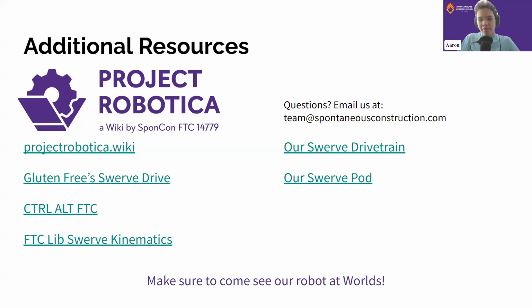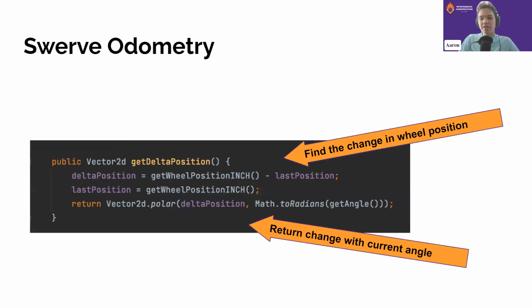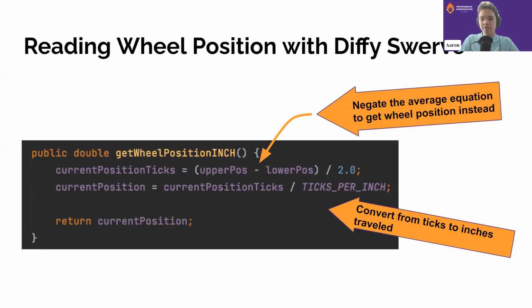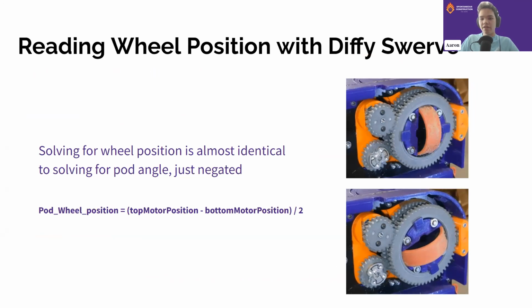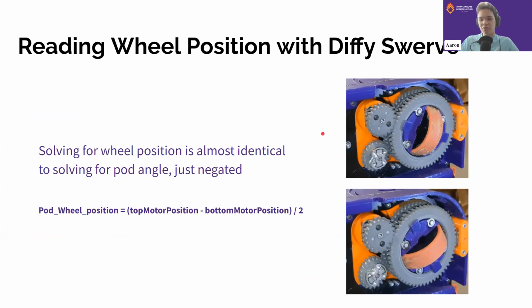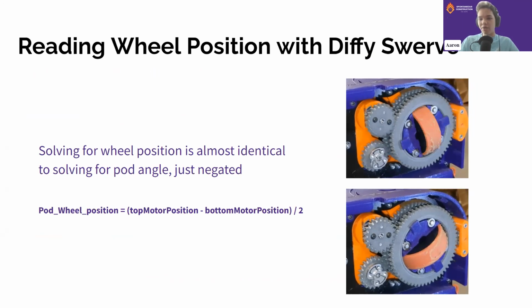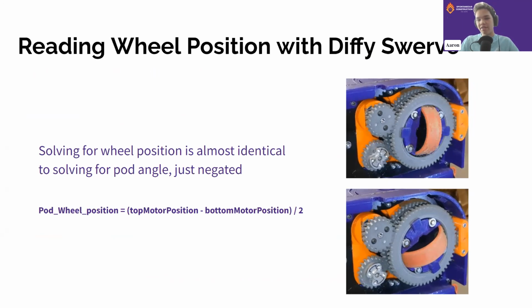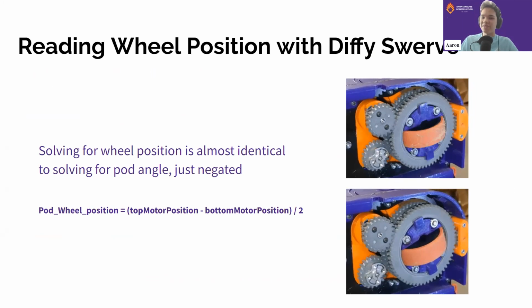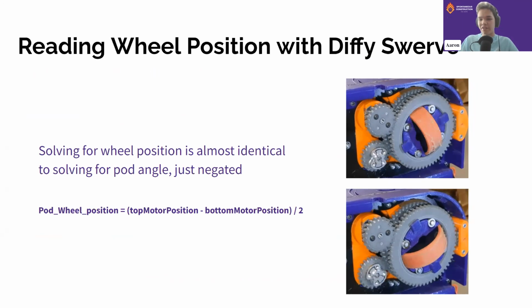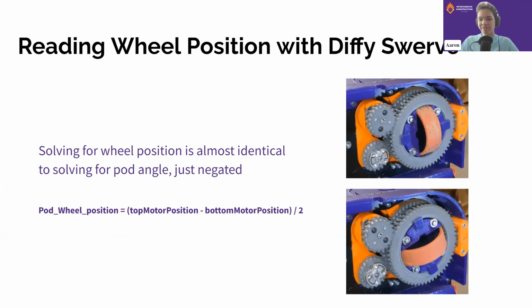There was a question by somebody about whether or not a differential drive is able to use servos for rotation. Because a differential drive uses 2 motors together to run, as you can see here, if one were a servo, both of the driving things need to basically be the same power. So they both need to be motors in this case, or you could have 2 servos, I guess, but the servos will be a lot slower for moving compared to motors. Just to add on to that.